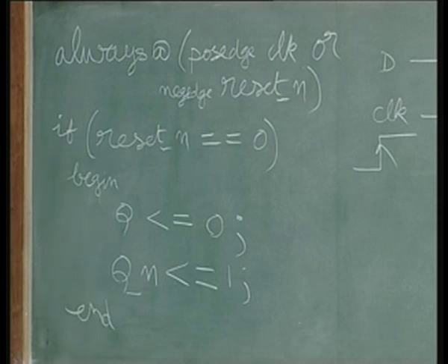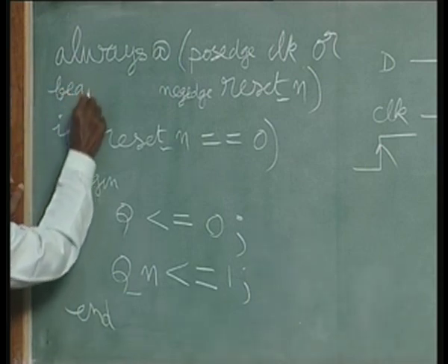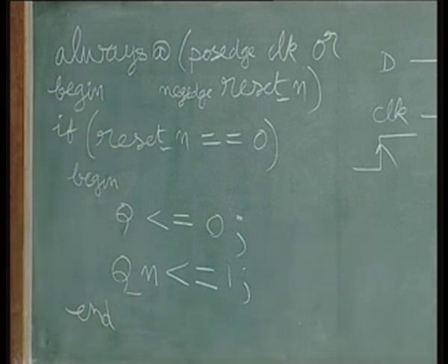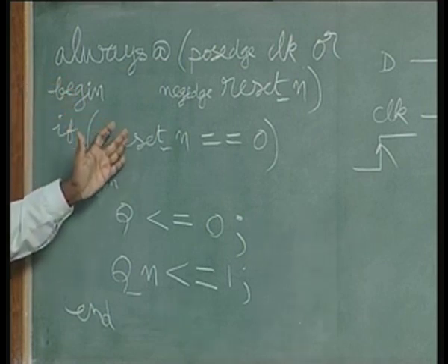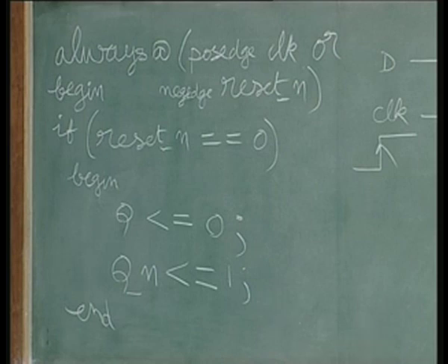After this, we have forgotten one more thing here, that is begin, and we should not forget an end corresponding to that. It is a good practice to follow indentation. For example, you can put begin here and start somewhere here, and try to avoid using tabs. Good practice will be to use manual spaces, because there will be a difference from editor to editor, and unfortunately you may have to migrate from one editor to another as we see different tools later on. Otherwise do not worry much about it. In fact, I am violating that by putting tabs. I hope you will avoid that.